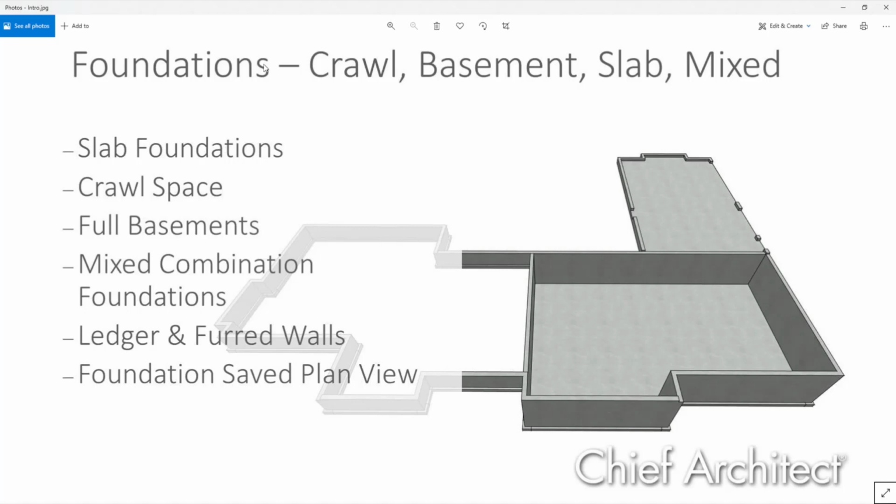Yeah, I think that, first of all, there's not an automatic way for the garage floor to slope in the program. You can take an elevation view and draw a slope line or put a pitch indicator on your floor plan view. And if you want to see it actually in 3D, I think the easiest way would just be to use your polyline solid tool in an elevation, and a 1/4-inch slope, whatever you're doing in there.